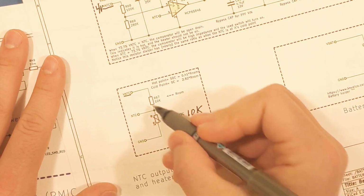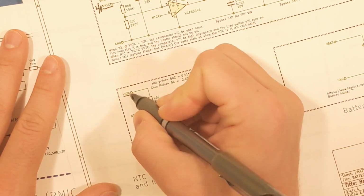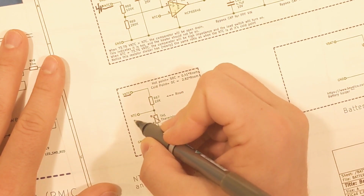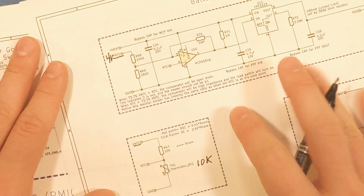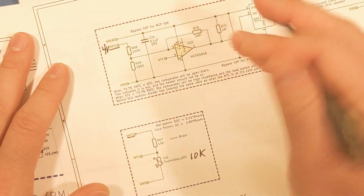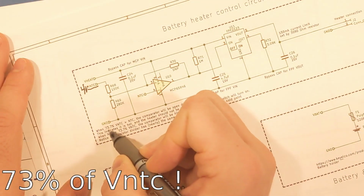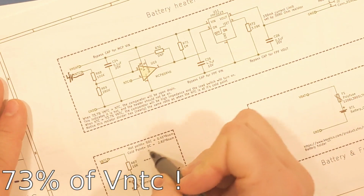VNTC, looking back down at our NTC circuit, is the bias voltage, and then NTC is whatever reading I generate from the thermistor itself. So I take that, this goes off to the battery charger circuit, and I use it again in this op-amp circuit. And as it works out, it's 73.7%, which is the same as the cold point.